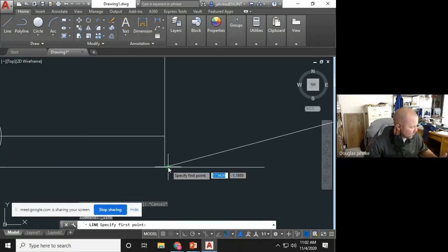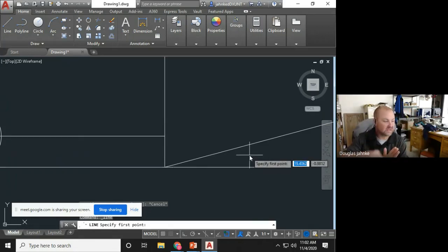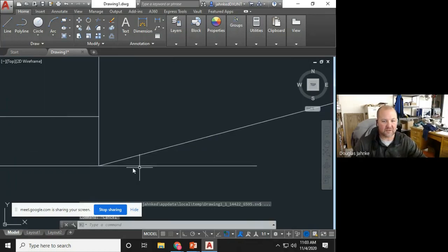Notice, everybody look at that drawing really close. Look for that 1.6. You see how that dimension goes 1.6 straight horizontal, right? It's not measuring it 1.6 up at an angle. Remember, shortest distance between 2 points is a straight line. Well, this is measuring horizontally at 1.6, and I'm going to show you in a minute how that's important. I'll come back to that.